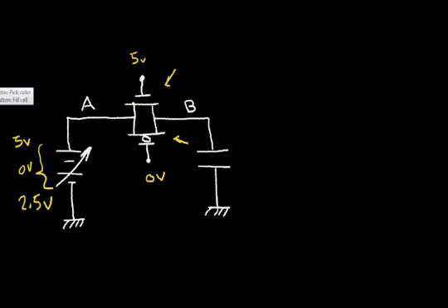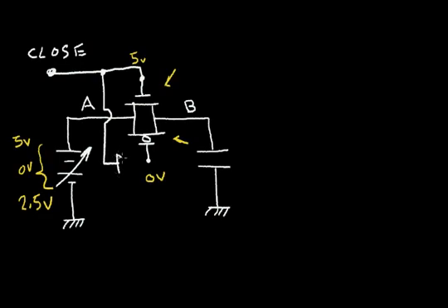So in a typical circuit, we might give this terminal a name. And if this voltage is high, our switch is closed. So let's label this node with the name close, which infers that a high voltage signal causes this NMOS transistor to close, but we also want the PMOS transistor to close. So let's add an inverter over to the gate of this PMOS transistor. So the output of the inverter will connect to the gate of the PMOS.